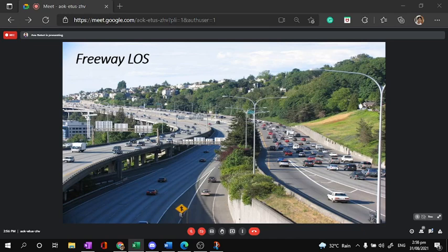To avoid so much congestion, where the whole road network is level of service F, you can segregate traffic flow. So this is going to the city, okay, urban area. When you arrive in the urban area, many vehicles enter. This is going away from the city, maybe to a town, province, or village. So there are fewer vehicles there. And this is maybe traffic going outside the city, but going to an airport or seaport area. So therefore, there is a lot of moving traffic going to these locations because a lot of people will be traveling. So this is segregation of traffic by level of service in a freeway condition.